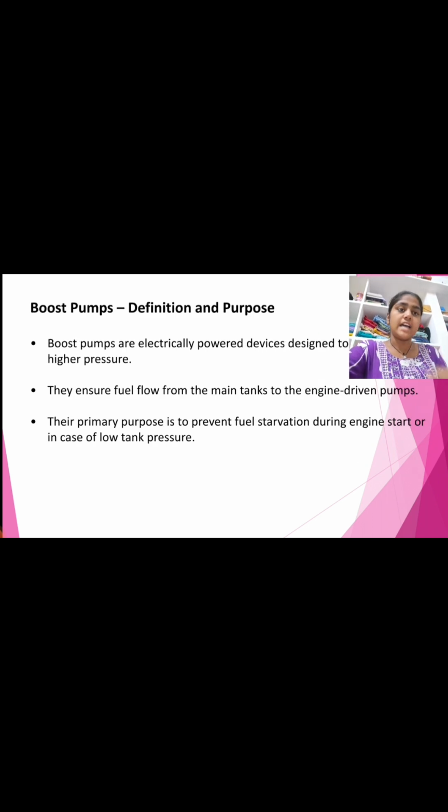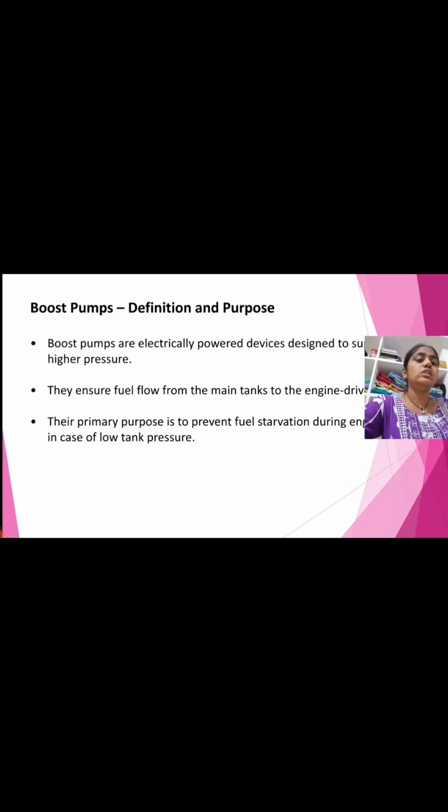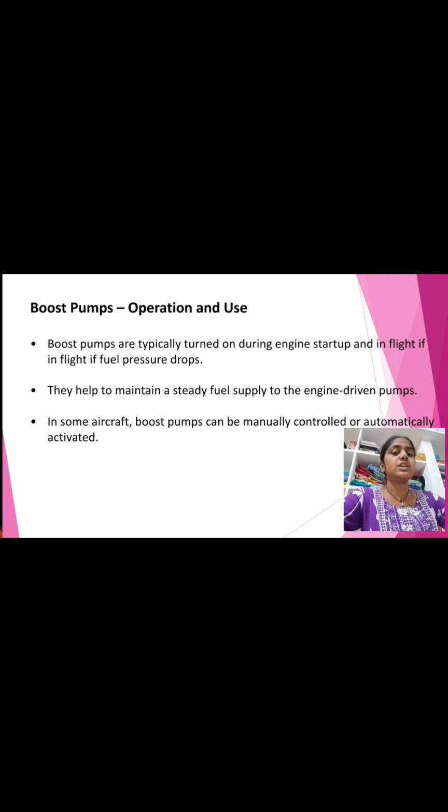Boost pumps. As we discussed, boost pumps are electrically powered devices designed to supply fuel at higher pressure. They ensure fuel flow from the main tanks to the engine driven pumps. The primary purpose is to prevent fuel starvation during engine start or in case of low tank pressure. Boost pump operations and uses: boost pumps are typically turned on during engine startup and in flight if fuel pressure drops. They help to maintain a steady fuel supply to the engine driven pumps. In some aircraft, boost pumps can be manually controlled or automatically activated.